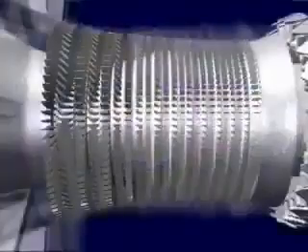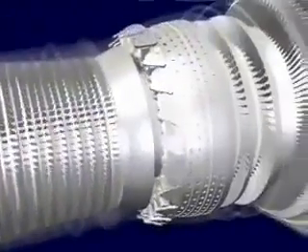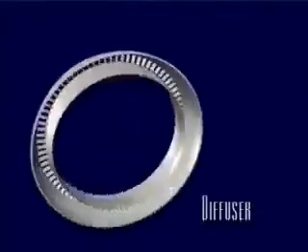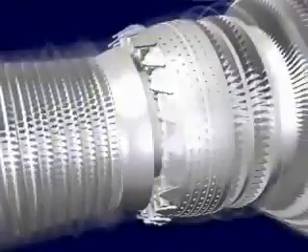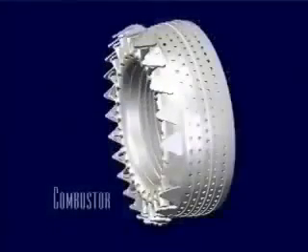After the air has passed through both compressors, it is 35 times higher in pressure and 1,000 degrees hotter than the outside air. The compressed air is now at the right pressure, but it is moving too fast to be efficiently ignited, so it enters a diffuser, where it slows down while remaining at the optimum temperature and pressure. The air then enters the combustor, where its energy level is greatly increased.